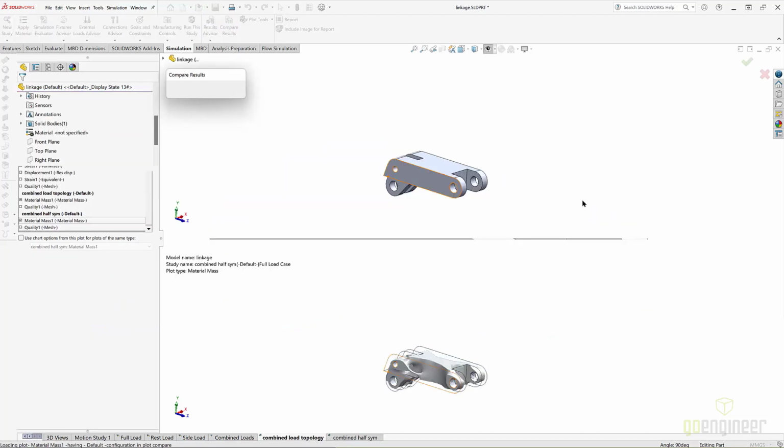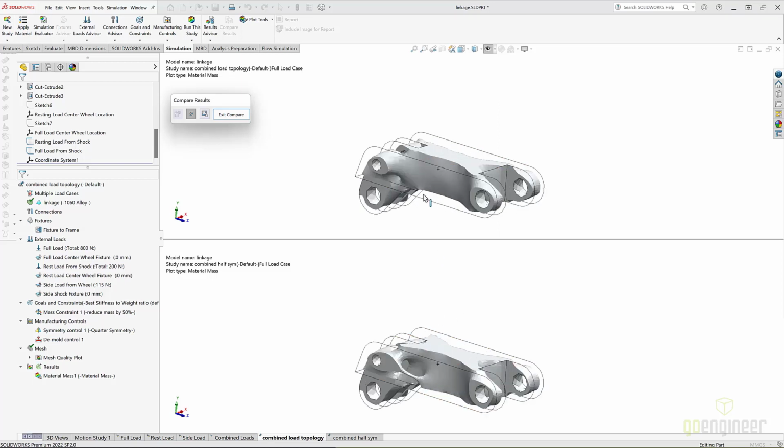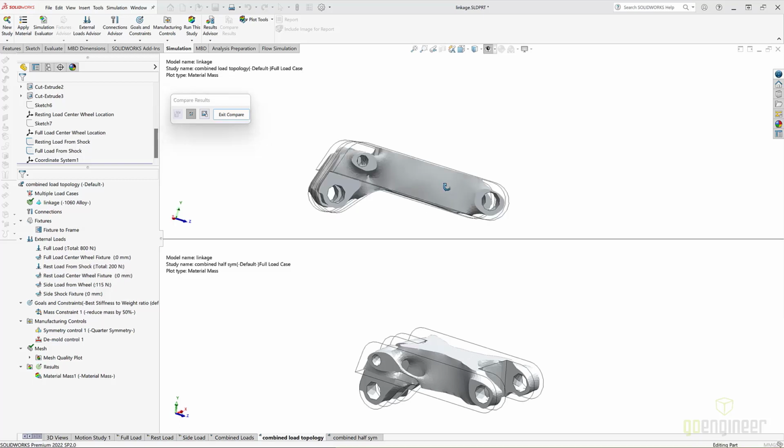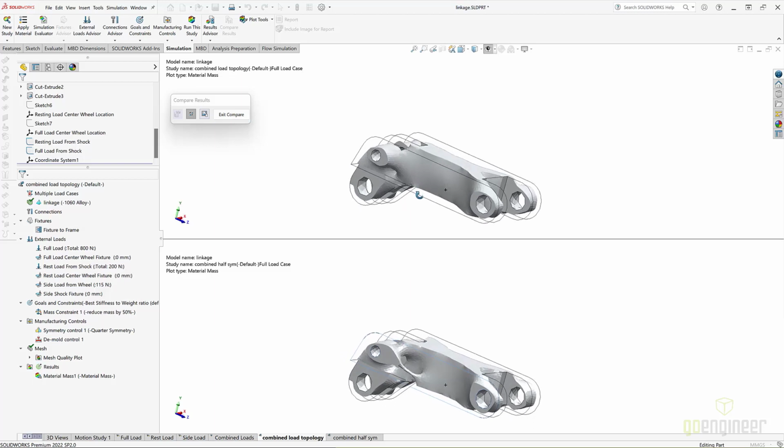As the top model loads in, the bottom shows the half symmetry model, with only 1 plane of symmetry to eliminate mass by, and the top one is the quarter symmetry model. As you can see, there is a difference in where mass was eliminated from the bike link. It shows that on the bottom one, we did not have any symmetry in the plus and minus y direction, but we did have some symmetry in the plus y direction for the top linkage.